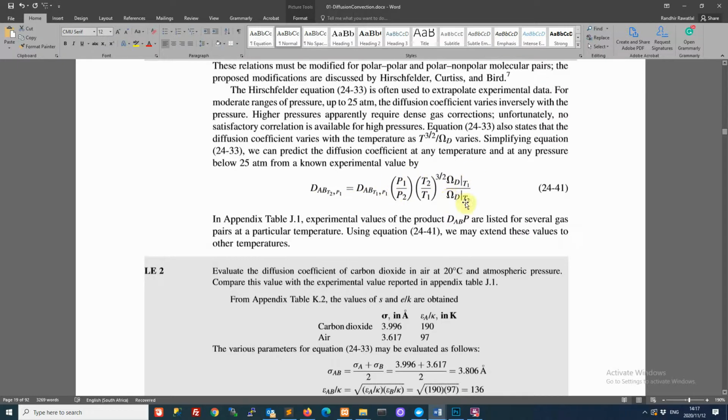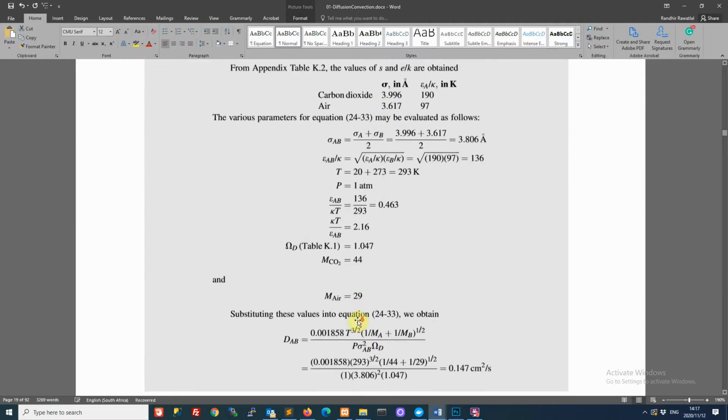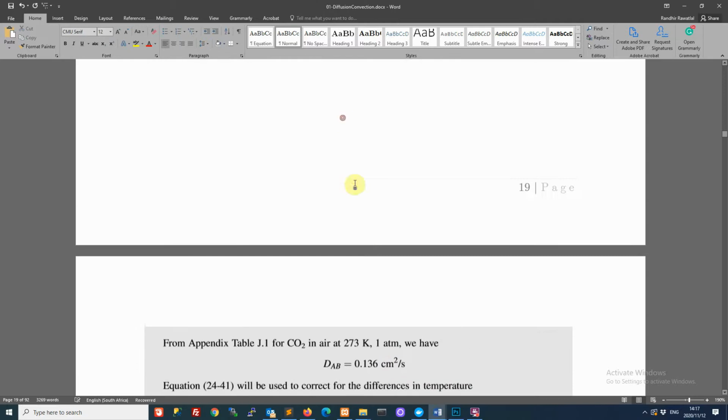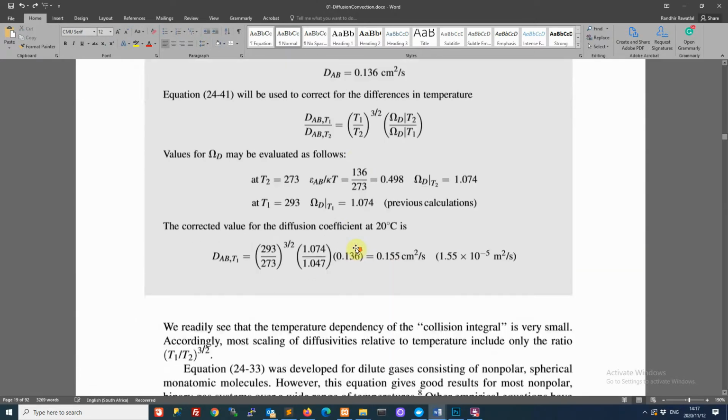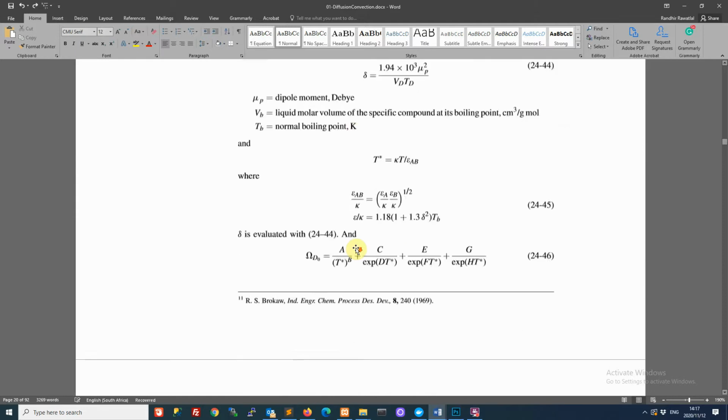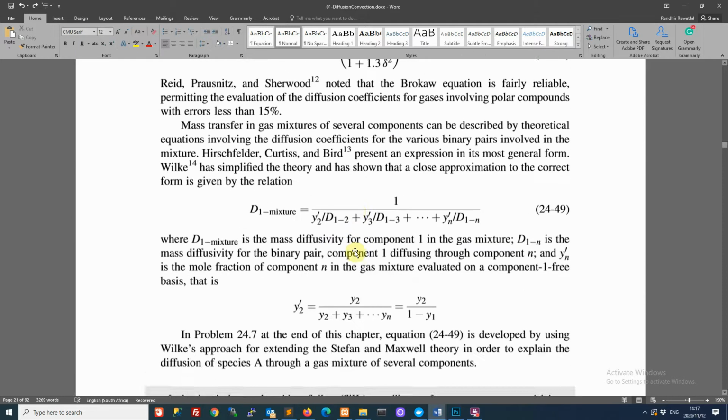And here you do have to be careful that if there are some other quantities involved in that relationship, which are functions of your operating parameters, then you do have to correct these as well. And then that's a faster way of estimating a new diffusivity. Okay, so there are lots of worked examples, and you can get used to some of the available correlations in this way. So those are some of the correlations for the gases.